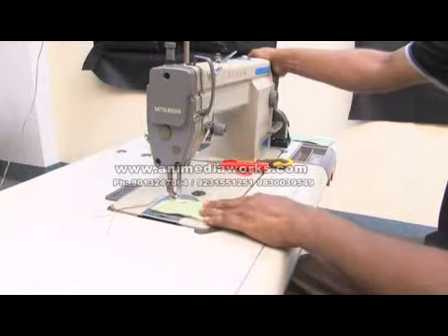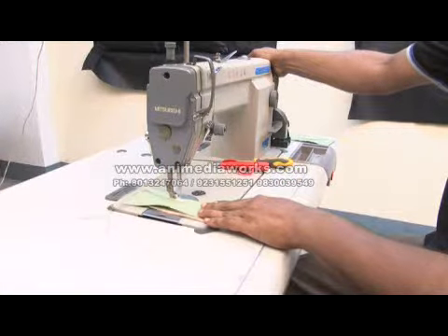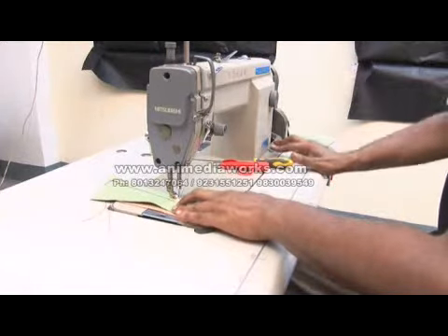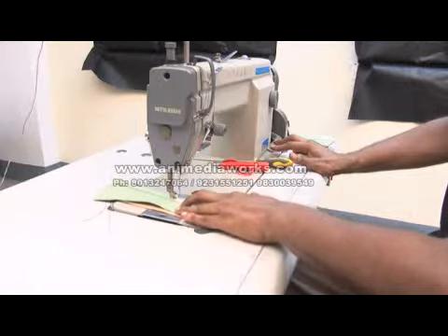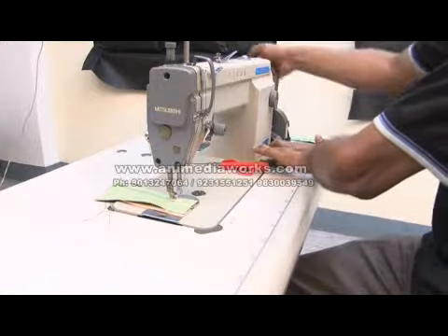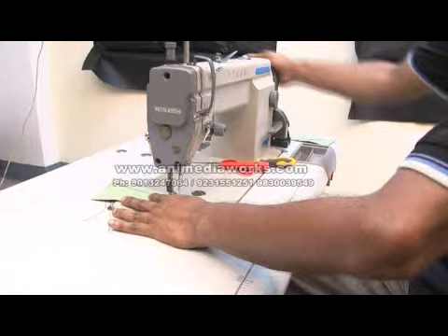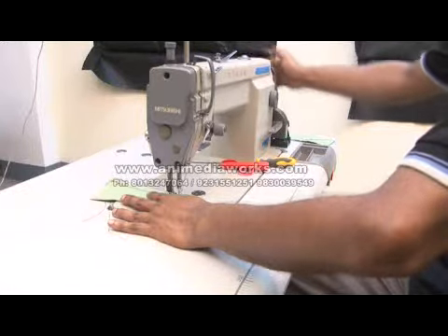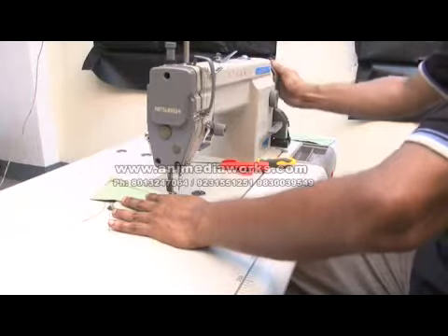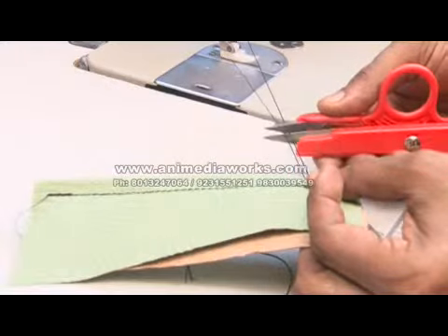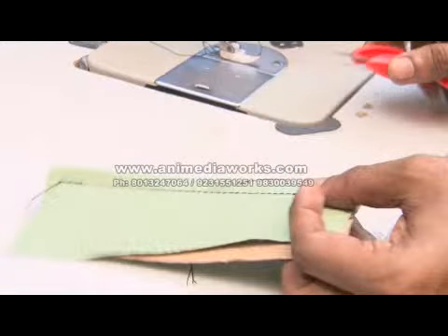For a lock stitch, use the lock lever to drive the machine in reverse. Position of the needle at both ends of the lock stitch distance should be the same to overlap the original stitch. This helps to prevent the stitches from opening. Use the knee lifter to release the material. Make sure the needle is not piercing the material. Use the take-up lever to bring the needle to the topmost position. Use the thread trimmer to cut the thread, always leaving a tail for the next operation.